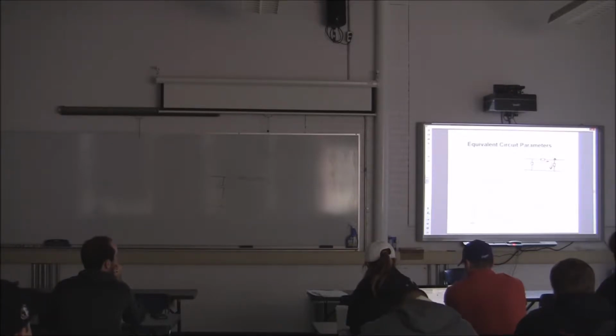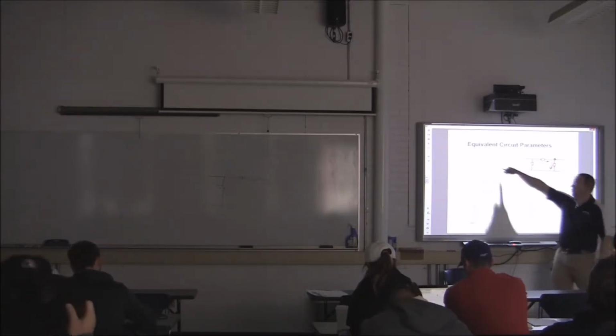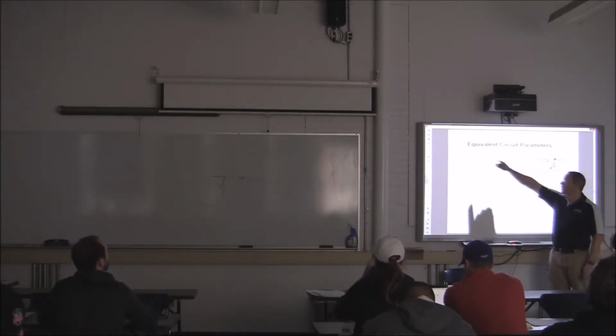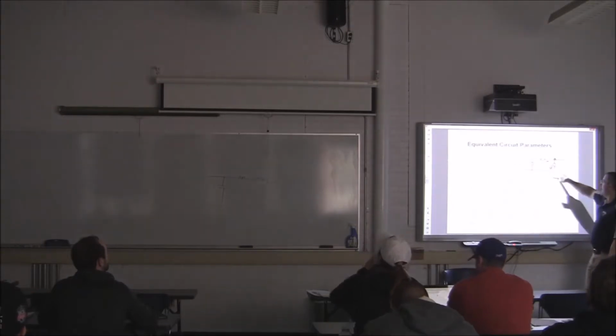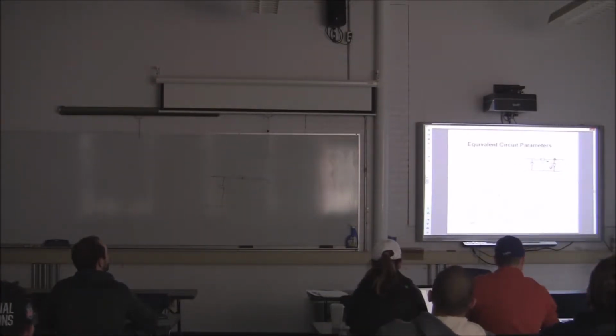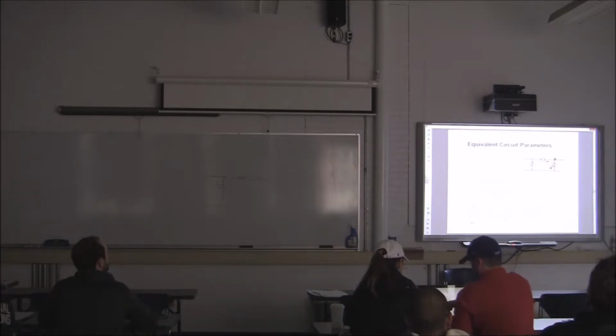What are the units of Y? 1 over ohms. So I don't divide by my element here. I multiply. This gives me amps. So this current minus this current equals my IR. Okay? Everybody see how I did that?